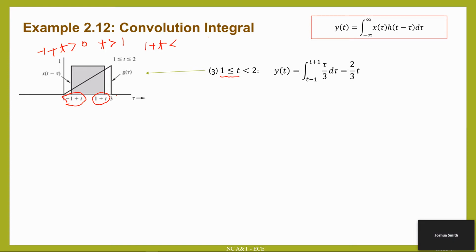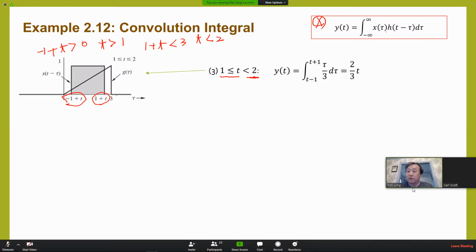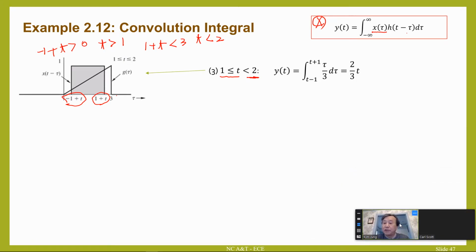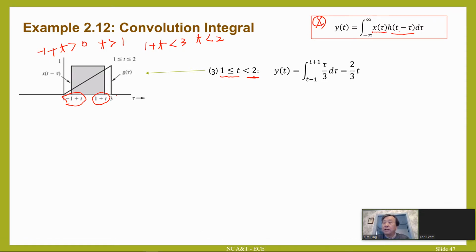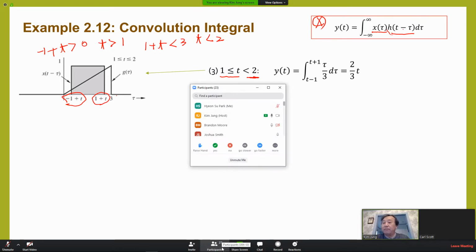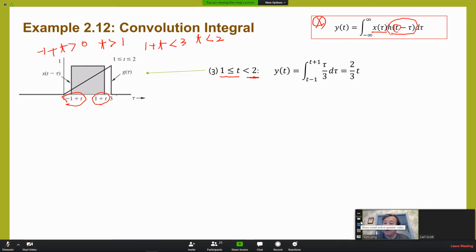Dr. Kim, just so I'm trying to understand this correctly, the convolution integral is about moving x of t through g of t. Are you shifting it through g of t? Okay, so this is a convolution. First, x of t changes to x of tau. Another function, in this case we use g, is g of t minus tau. So t minus tau changes the tau domain, flips, and shifts by an amount of t. That's the process, and then multiplication and integration.